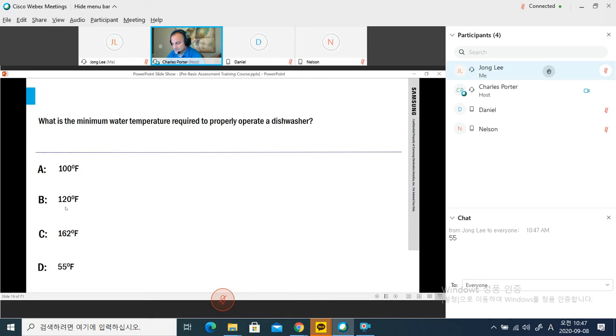That being said, I always give you guys this caveat. That's not going to be your only reason that unit is not working. So all of our dishwashers do have heaters that heat the water. And theoretically, that dishwasher should heat that water up to that minimum temperature. It's got a thermistor in there. It knows if it's not right. It won't work as efficiently if it's really cold and it's got to do all the work heating it up, but it should still do it. That being said, it's still a good idea to make sure that temp is at least pretty warm, if not hot, when it's going into the unit.